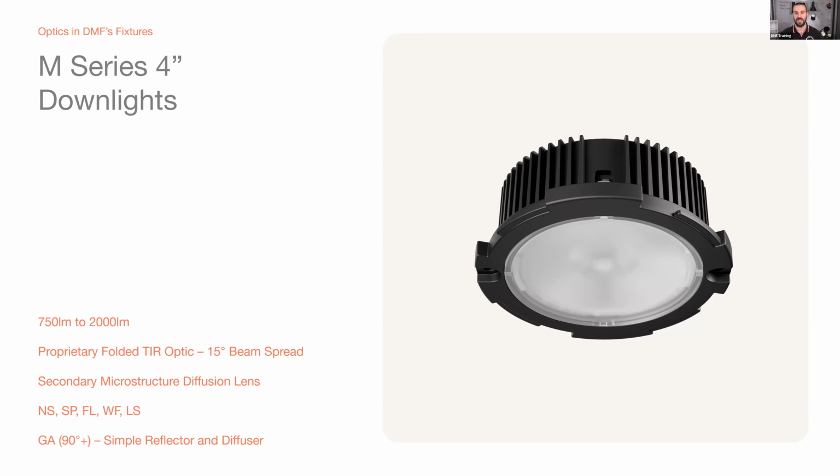It's not a crossbeam optic because in a 4-inch aperture, crossbeam optics and getting that sort of reduced glare on the trim is a lot less paramount. That has more surface area to spread out, and those excess light rays don't tend to have nearly as much effect as they do in smaller aperture fixtures.